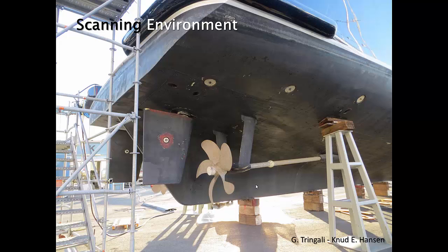This particular survey offers us also some interesting challenges. If we look at the top right hand corner, we can see a reflection of a mast in the hull form. It's interesting at this point we see that this vessel has a very shiny surface, and the laser failed to capture anything above the waterline that had this shiny finish. In fact, on the transom, at the stern there, we can't see any of that at all. It's just purely reflecting the white sky.